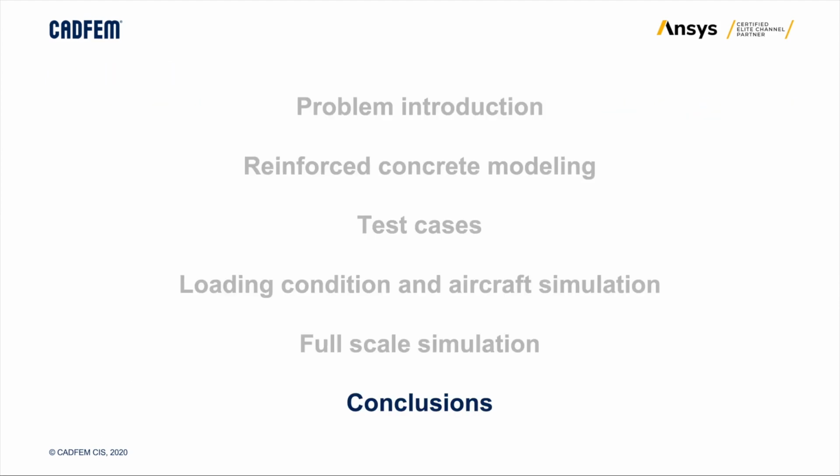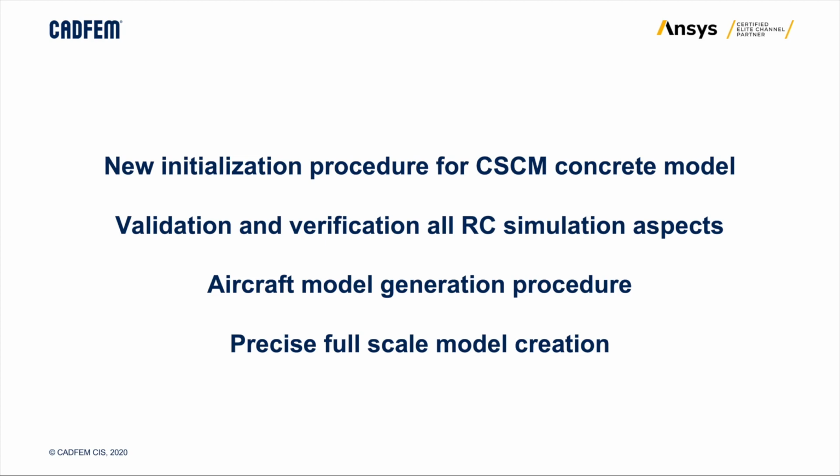Let's see the conclusion of our simulation methodology. I want to mention that we developed a new initialization procedure for the CSCM concrete model, and this procedure allows us to significantly reduce the error in strength estimation, sometimes from 30 to 5%. We validated and verified this procedure and all other aspects of reinforced concrete simulations.